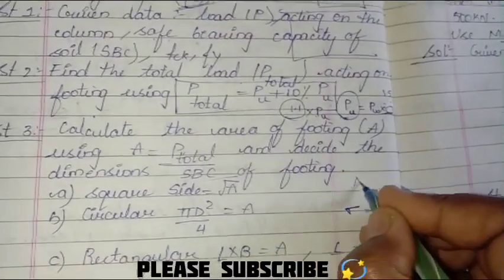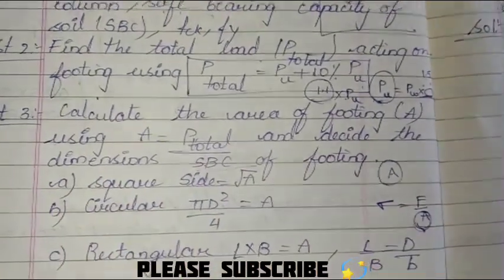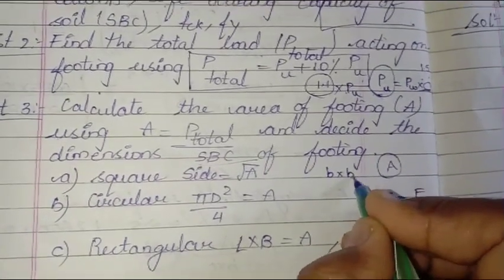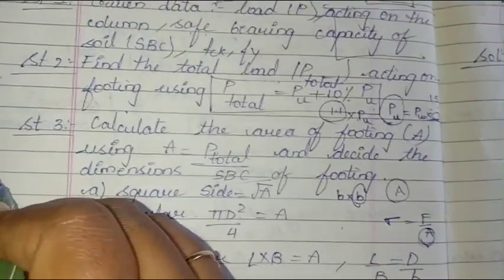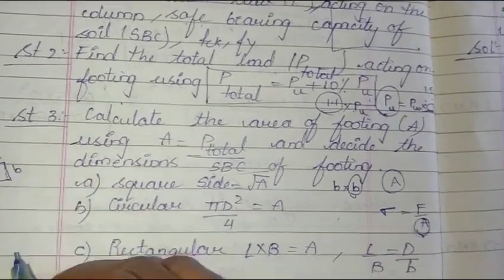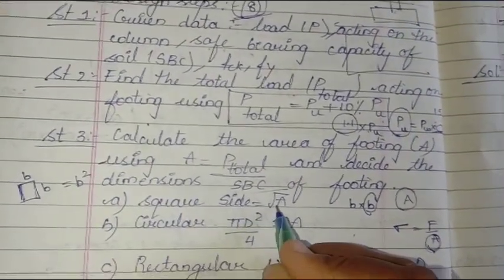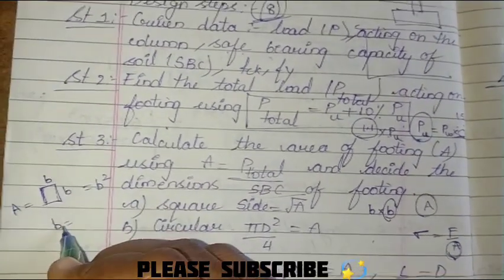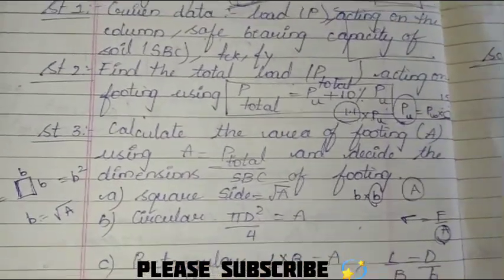Once we get the area, we will be calculating the square side. We know that for a square, the area is breadth into breadth, because here the breadth is equal to depth in this case. Whenever we are talking about the square footing, both sides would be the same. Area is nothing but B by B, so it's going to be B square. If area is B square, what would be the B? B is nothing but root A. So that is why it's root A over here.